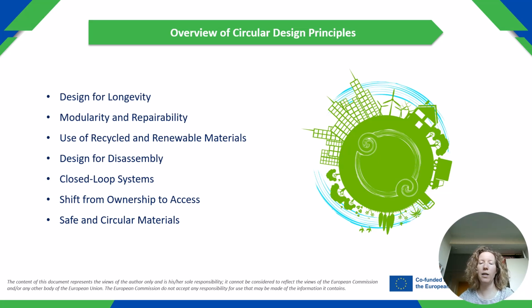Use of recycled and renewable materials. Prioritizing materials that are recycled or renewable helps reduce the environmental impact. This includes using reclaimed wood, recycled materials, and biodegradable materials. Design for disassembly. Products are designed so that they can be easily taken apart at the end of their life cycle. This facilitates recycling and the reuse of components.